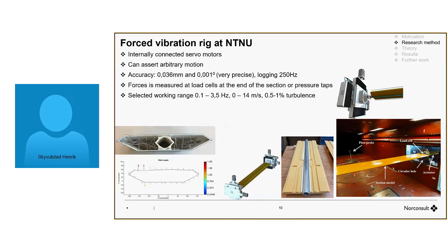I've seen some work done on this with pressure taps. We have pressure taps around both decks, and then you can tell where the nonlinear forces are coming from. But these are done mainly on static coefficients, not on dynamic tests. Because if you could find a linear correlation between the movement and angle of attack of the first girder and the wind forces on the second girder for the different frequencies, then this could be a good explanation for many non-linearities. But I'm not sure; there are certainly many other difficulties in the process.